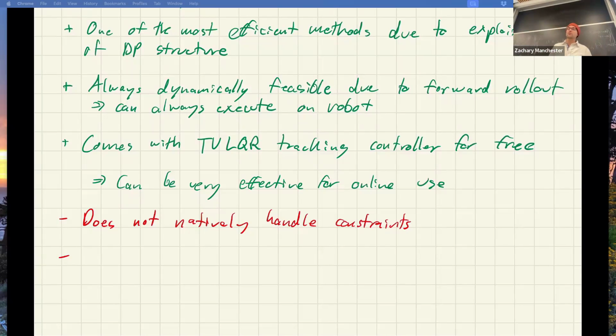In particular, that's useful in, for example, maze-like situations. We have a lot of obstacles. These methods often struggle with getting around obstacles. So a really common move would be to use something like a sample-based planner, like an RRT, to find some kind of pose trajectory that makes it through the obstacles, and then use that as an initial guess of your state trajectory for this guy.